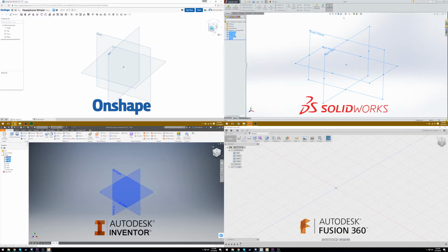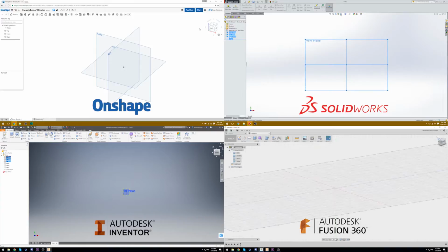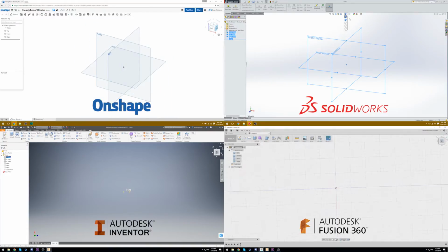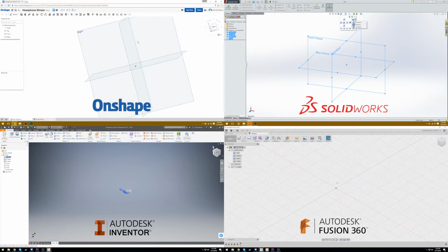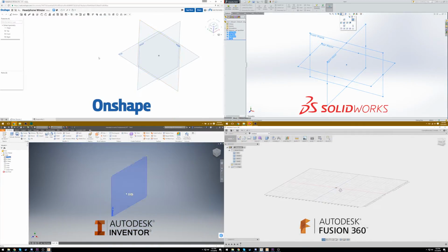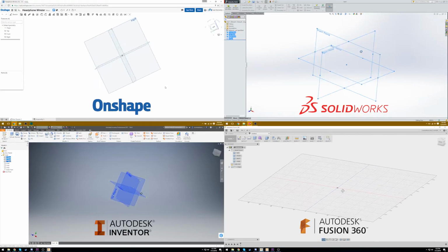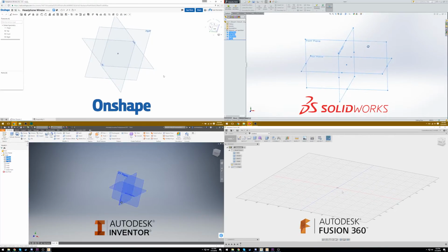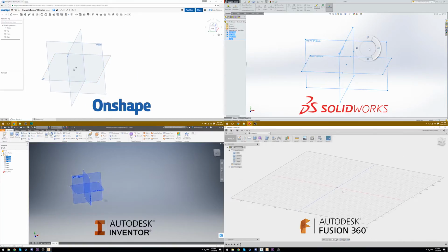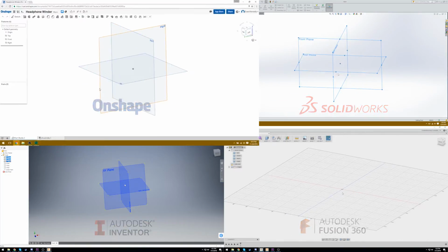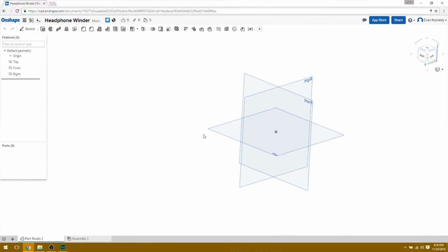Up the top right hand side here, this is what I call the view control box, and you can use this to navigate around your camera. This is especially useful if you're on a laptop and you don't have an actual mouse. If you're using a touchpad, you can click on these views or on the corners or on the edges, for example, and it will take you to that view so that you can sort of see what's going on. Alternatively, you can use the mouse for this, so I'm holding down right click and dragging around, and that lets you sort of pan around. You can also press down your scroll wheel to pan like this, and you want to scroll up and down to zoom in and out. So without further ado, I guess we'll start making our object.